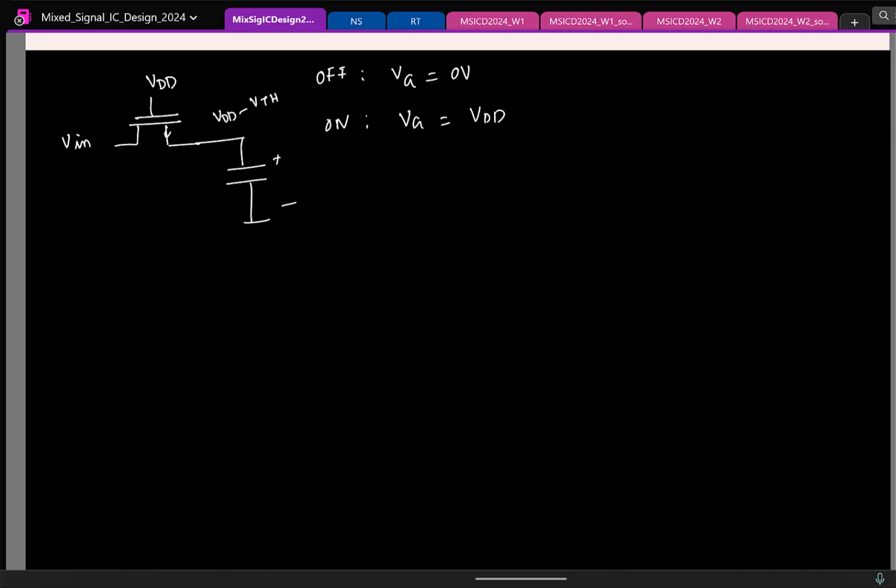So why is this happening? Why did you say that last class? Yeah, see, the thing is, let's say input is greater than VDD, for example. We are assuming that the MOSFET is in saturation. No, MOSFET is never in saturation here. Think about it. If MOSFET is on and acting like a good switch, V in appears here.